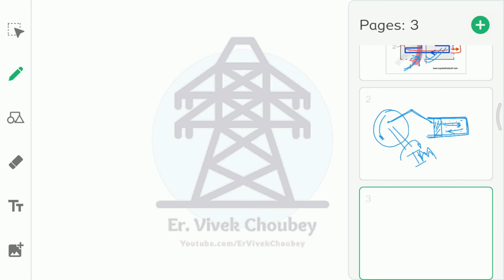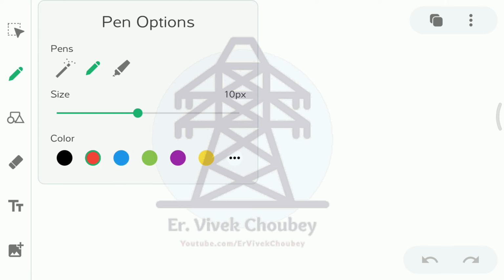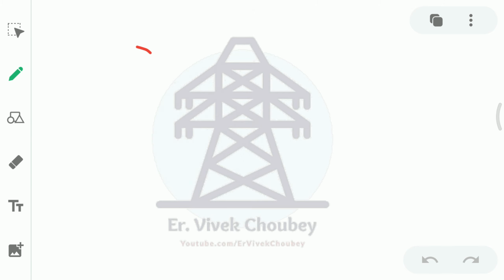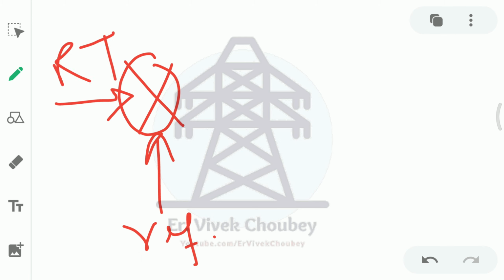Now we just saw that to drive a compressor, an induction motor is required. Now in a normal AC, what happens? If you understand it in terms of a control system, here is our control system. There is a comparator. A comparator is a device, as we all know, which compares two or more values and sends an output. With the help of a remote, we set a reference point, and then there is our room temperature.